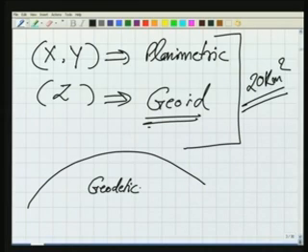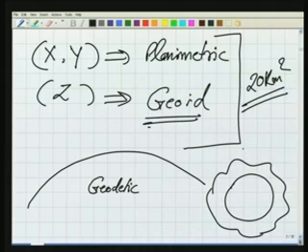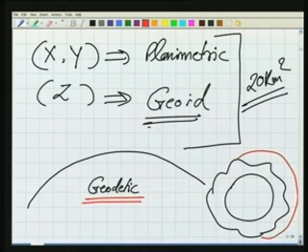When we are considering the curvature of the earth, this is truly the case. The other example which I gave you was our earth, where you wanted to fire a missile from a point here to a point here. In this case, you need to consider the curvature of the earth. It has to come into account. So in that case, the surveying that we will do will be geodetic surveying. However, for our engineering projects, we can very easily and comfortably consider the surface of the earth to be flat, and that is the surveying which is called plane surveying.